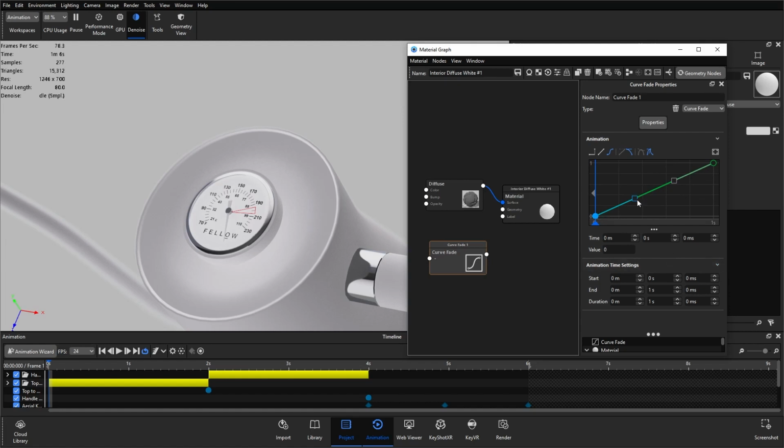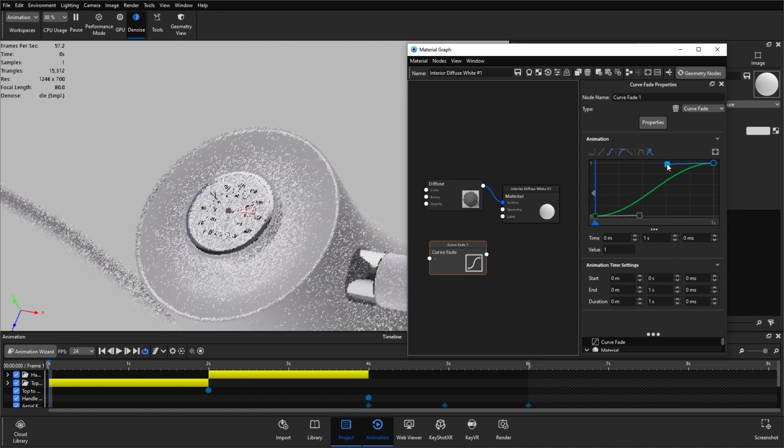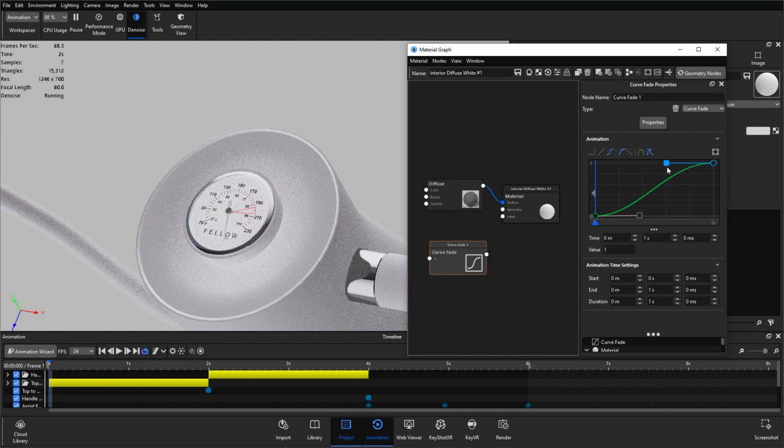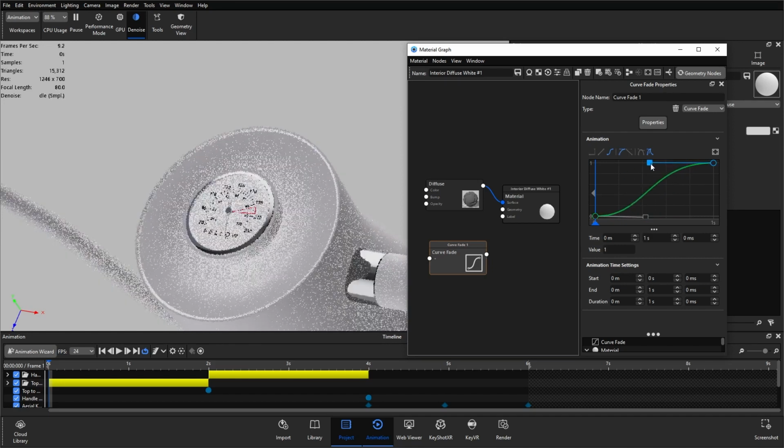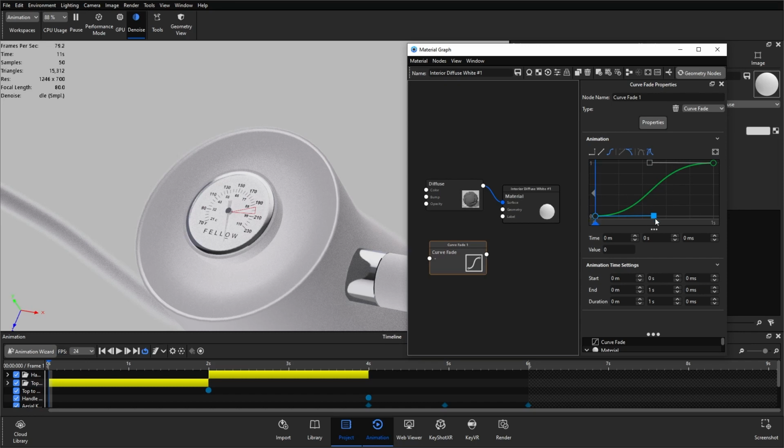You'll be familiar with this type of graph if you've ever played with the custom motion ease in and out with any of the other animation tools. If not, you can see those square points are handles for each keyframe. So you can manipulate the shape of the graph just by pulling and dragging these around. The way I've got it set up at the moment, it's going to ease into the motion, or ease into the change of parameter. Then once it gets around this mark here where my mouse is, it's going to ease out and slow down.